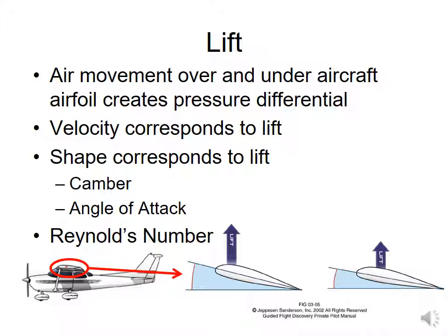Think about deflection. But also the specific shape of the airfoil affects lift. If you compare two different airfoils, the one with the greater camber is going to produce more lift. Think about Bernoulli and Coanda effects. We will discuss the Reynolds number, which takes into account the relative velocity of the plane as well as the length of fluid flow around the airfoil, which allows us to extrapolate and compare airfoil performance.